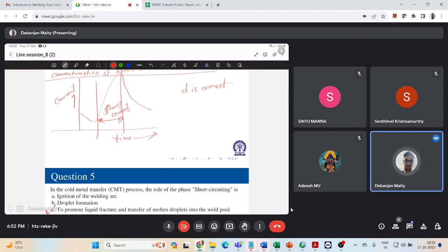In the powder bed process, the beam size is limited, and maintaining a huge amount of powder is very difficult. Correct? So here your beam size is very limited. This process requires some post-processing to remove the extra parts and for smoothening and finishing the surface, right?